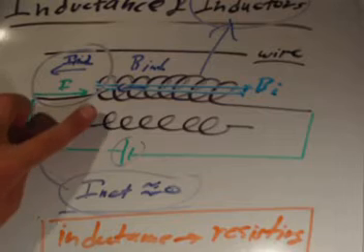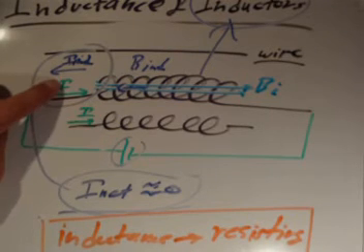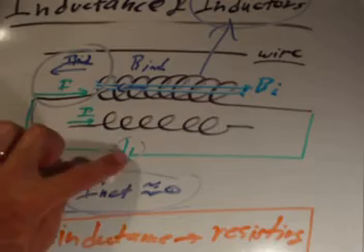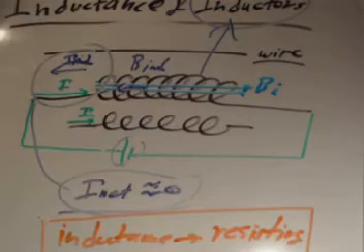You're trying to go from sort of zero current to some maximal current, perhaps predicted by Ohm's law, that this battery is trying to pump through this otherwise resistive system. That's a big change in current. And the bigger the change in current that you try to force this inductor to undergo, the more it's going to resist it.